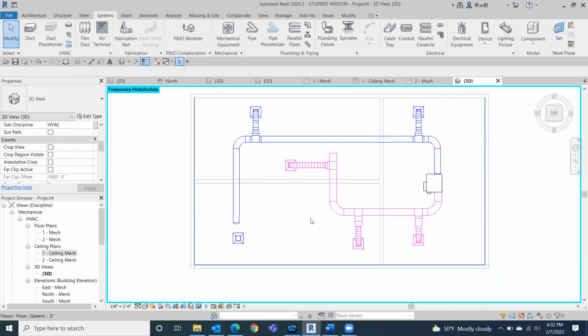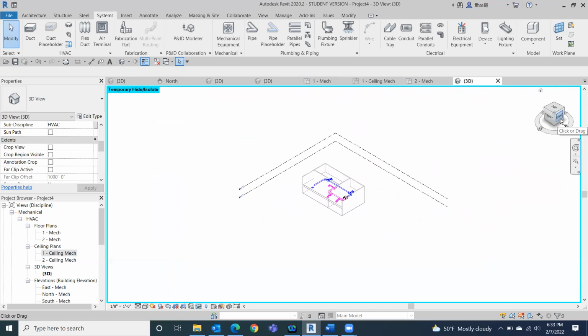Thank you. But I'm looking at these. I've never seen a house where there's a return in every room. Is that practical? Oh, for a house that's different. Remember, we're doing commercial. Yeah, this is commercial. We want a return in every room for commercial. If it was residential, you would only need one. Okay. Refer back to the mechanical presentation we looked at in the beginning.